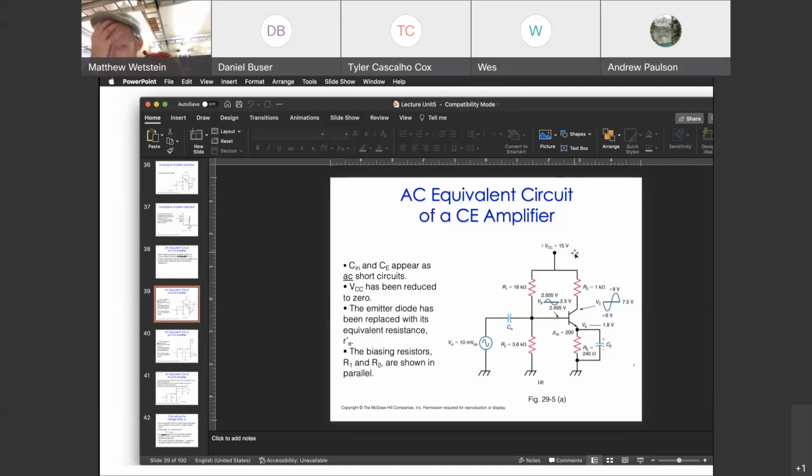That's a good question. I don't have a pre-memorized answer to that, but we can work through it. So let's say that the base current swings up. So we're applying more base current. That means that we're applying more current through this path, which means that the voltage across the transistor necessarily is going to go down.